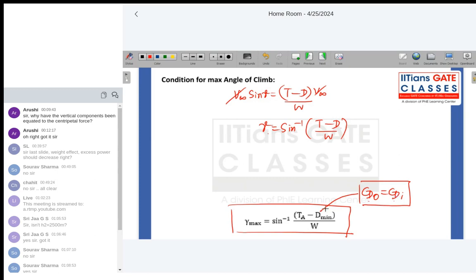So, if you see, rate of climb maximum occurred at a condition for piston engine aircraft when power required is minimum. Same for jet engine aircraft, it has occurred at a different condition. But if you see the climb angle maximum, it occurred at a condition where drag is minimum. Both the conditions are completely different. So climb angle maximum occurs at a different velocity, and rate of climb maximum occurs at a different velocity.